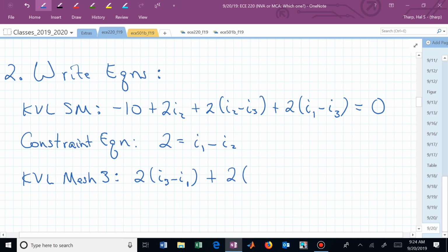The horizontal resistor from left to right is now I sub 3 minus I sub 2 times 2. We experience actually a voltage rise, so that's a negative drop. That's minus 6. We entered the minus 6 terminal of the voltage. That comes out immediately as minus 6 plus, just to emphasize the resistor, 1 times I sub 3, and that gives us 0.